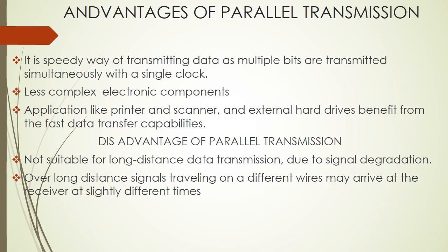So here are the advantages of parallel transmission. It is a speedy way of transmitting data, as multiple bits are transmitted simultaneously with a single clock. Only one clock is enforcing those data to be transmitted in different wires, and it is easier for them to go faster since they are using different cables. There are also less complex electronic components, so the design is not that complex.